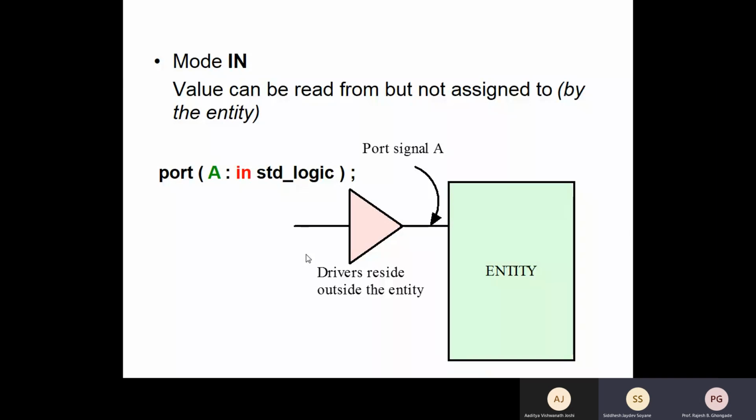No, we don't want amplification, so it will be the voltage follower mode. If you remember the voltage follower configuration, the input impedance is supposed to be very high and the output impedance very low. That enhances the sinking and sourcing capability.